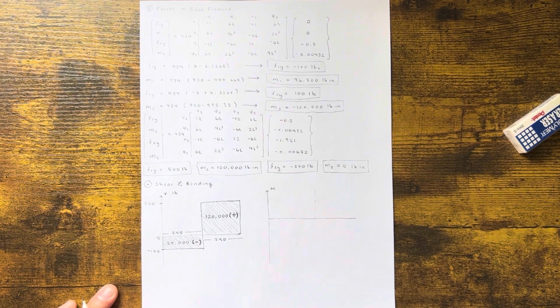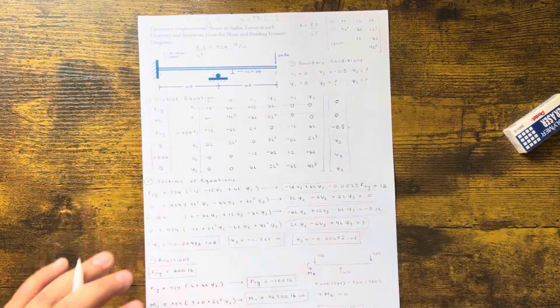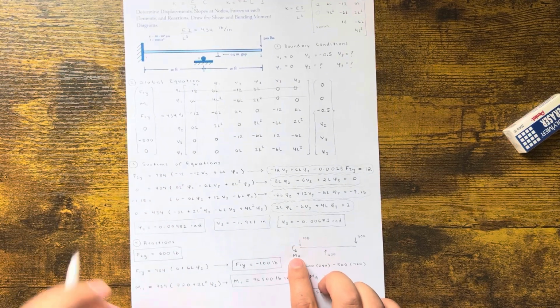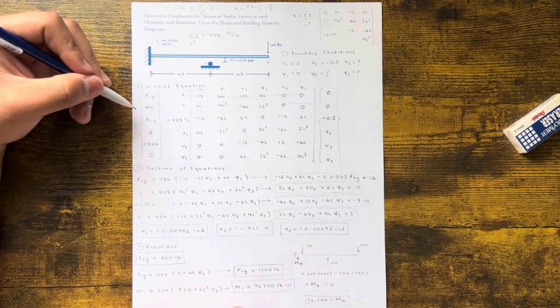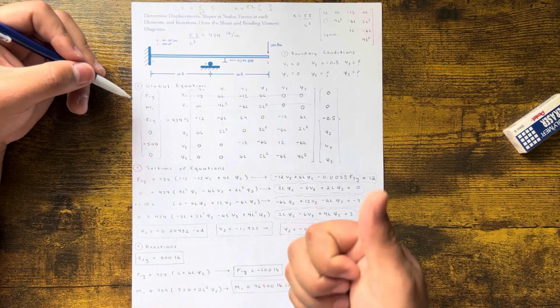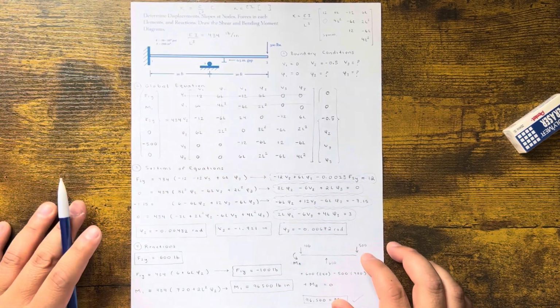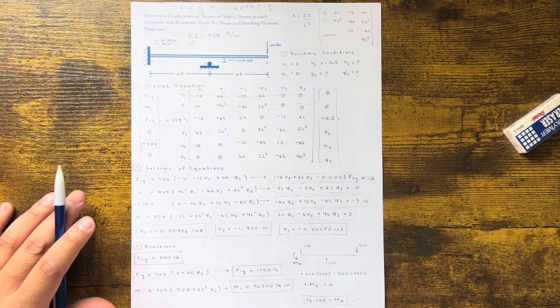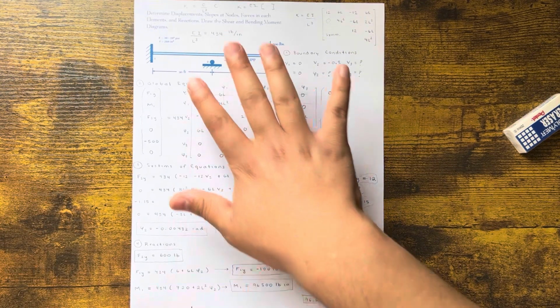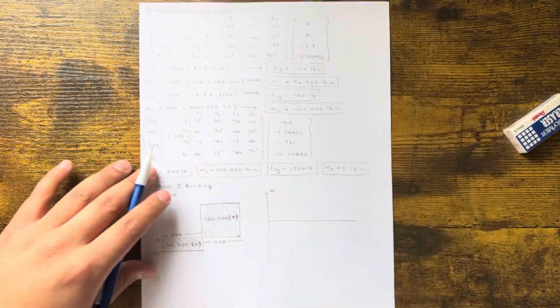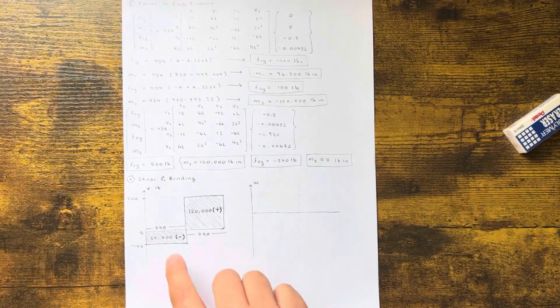So to do the moment diagram, first you have to see what moments are acting on it. In this case, MA is a moment, right? Remember? M1 was 96,500. So that's a moment acting on the diagram. M2 was 0, M3 was 0. So nothing's acting, I mean, M1's the only one acting on the diagram is what I'm trying to say, okay? Everything else is gonna be because of the shear, if that makes sense.